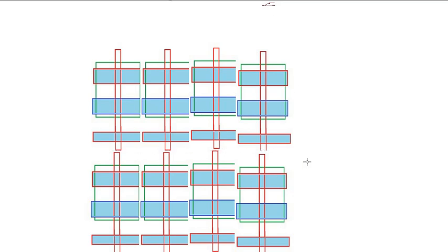Just for the sake of explanation, I'm arranging all the devices next to each other. Assume these are all the diffusion devices. Diffusions are continuous, and the metals are connected this way when you place or share the diffusions. Now, this is a kind of self-aligned dual patterning setup, wherein you have just turned on the options and all the colors are shorting with each other. You know that these devices are separate from each other.